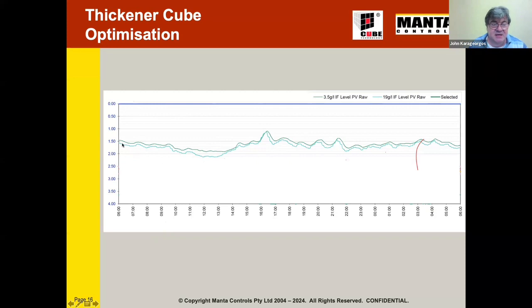So you can see here, and this is through a whole day, and this is dynamic. This is the particle size distribution changing through the operation, even through a day, hour by hour. So you can see here, nice and tight, we're actually settling really fast. Over here, we're slower. If this is a sulfide ore, which it was, there could be a little bit of talc, a little bit of clay coming through during this time, and then we'd start to up the flock dose at this point here.